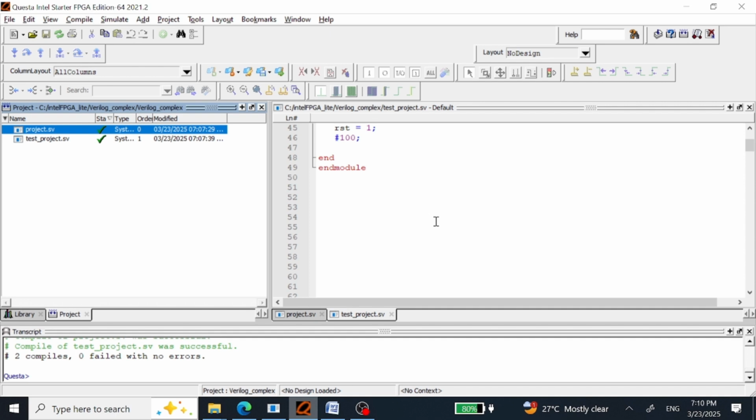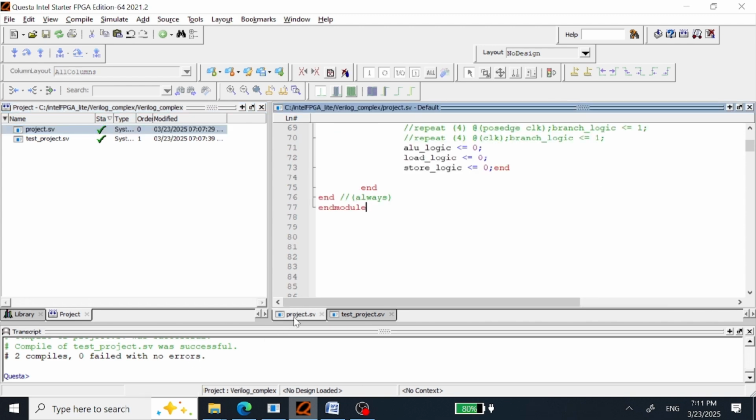In the first video I showed you mostly using the after statement of VHDL and the similar way in the SystemVerilog program. Now I am going to show you in this video the delay of the signal using the wait for statement, mostly in VHDL, and the similar way with which we can delay a signal in SystemVerilog as well. So this is a SystemVerilog program first, and let me first explain it to you.